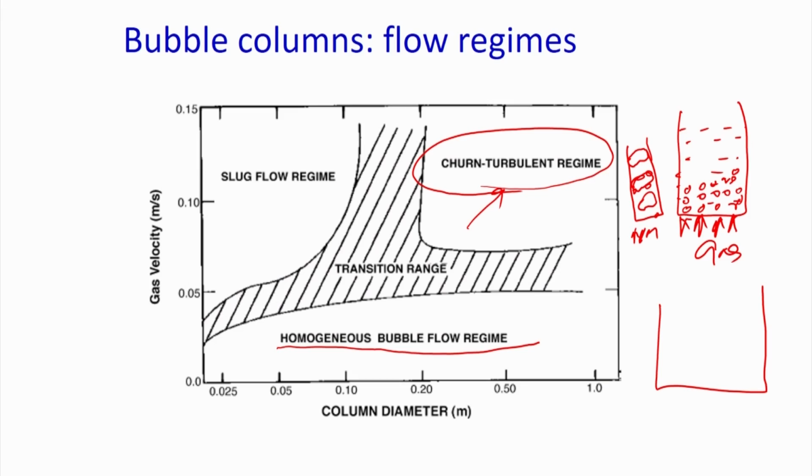Similarly, for experimental measurement techniques, if you are operating in the bubbly flow regime, any technique will work because your volume fraction is less than 5%. If your gas holdup increases, the volume fraction of the discrete phase will be too high, the analysis will be difficult and optical based techniques cannot be used. Even intrusive techniques cannot be used, and you have to go for RPT or MRI or PEPT kind of technique to analyze the system. This system is very typical, very difficult to analyze, and most of the industry operates here.